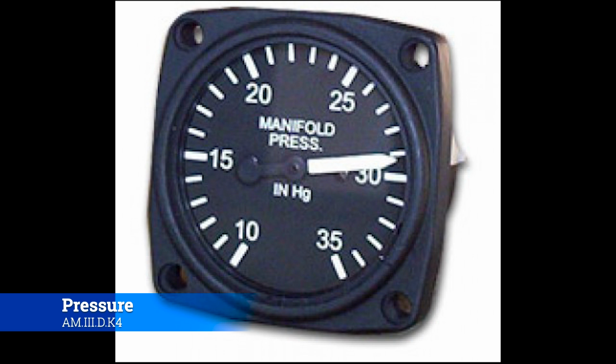All right, manifold pressure. Now, this is a real important one. Whenever it says manifold pressure, the manifold it's referring to is the intake manifold, okay? Now, the manifold pressure is going to help you obtain the correct power setting for the engine. It's going to say, hey, look, we know that for this mode of flight, for this maneuver, we've done the math, and we know that 30 inches of manifold pressure is what we need to see in order for the engine to produce sufficient power to do this thing, whatever the thing is. Takeoff, landing, you're going to do a barrel roll, whatever.